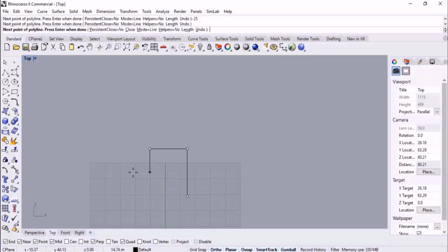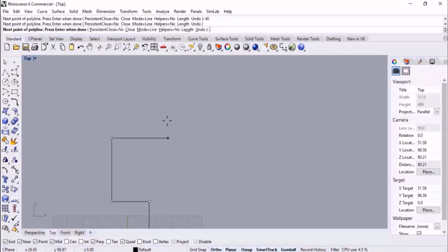As you can see, when you are specifying the length, we are not able to specify the direction. While when we specify the direction in AutoCAD, meanwhile entering the length, the line will be sketched. But here is different. We sketch the line in 2 stages, specifying the length and then the direction. So this was the difference between AutoCAD and Rhino in sketching lines.